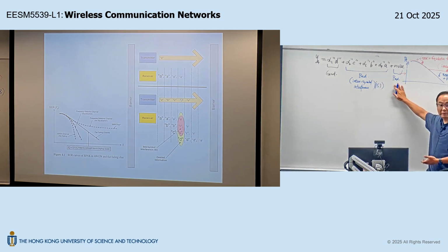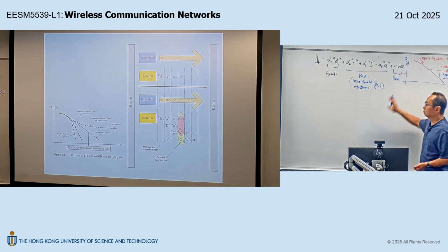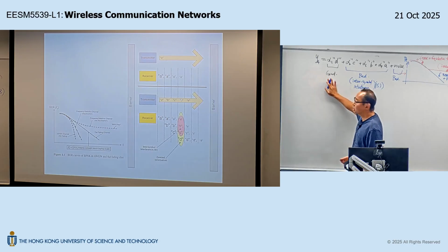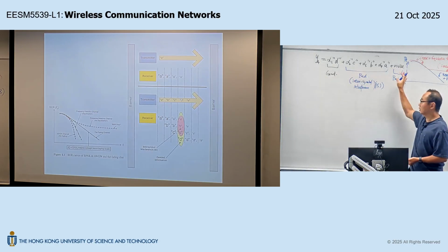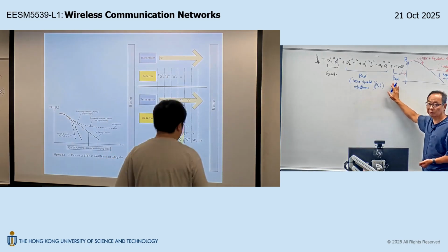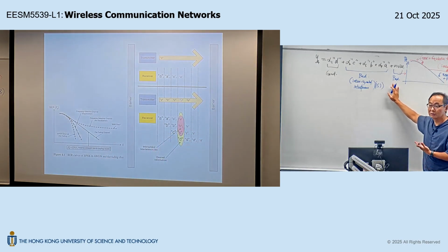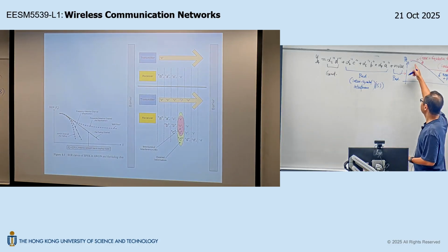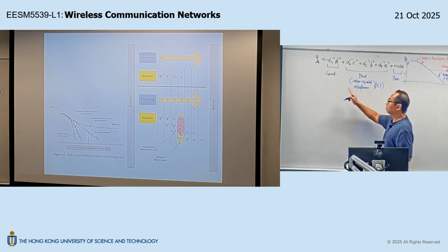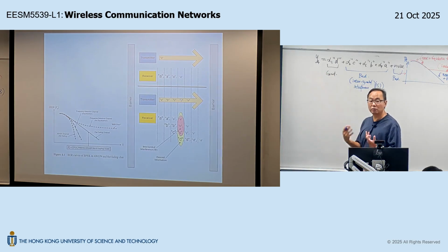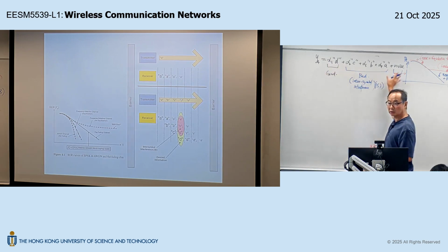The noise, of course, is the background noise, which is bad, right? It's a contamination. Okay, so the observation in the 4th time slot consists of a good term in the presence of 2 bad terms. One is coming from your self-interference. The other is coming from background noise. Okay? Now, of course, we can see that the error probability depends on the quality of this Y4, right? The quality of Y4 is basically the power ratio of the good term over these 2 bad terms, right?